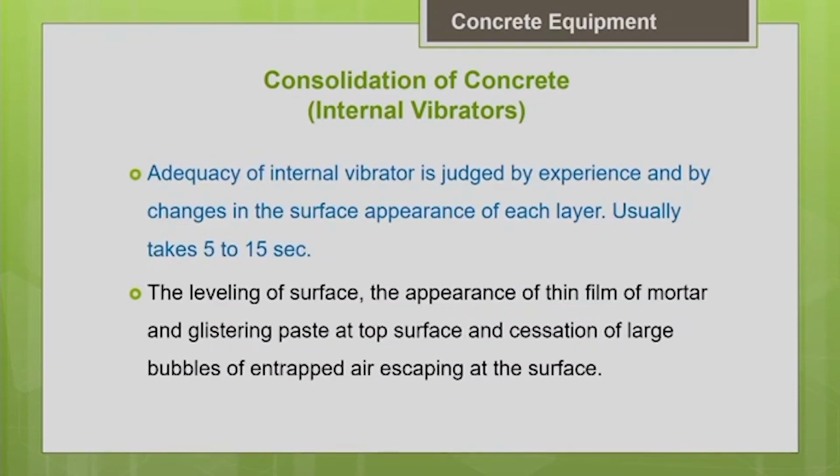So how long should I vibrate at a particular place? Usually we take approximately 5 to 15 seconds, but it depends upon the consistency of the concrete.